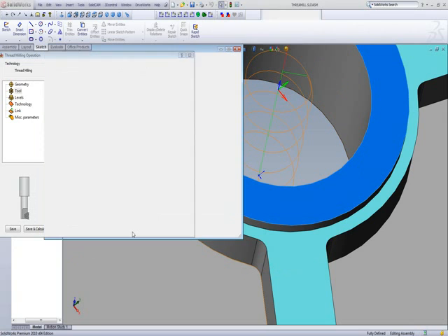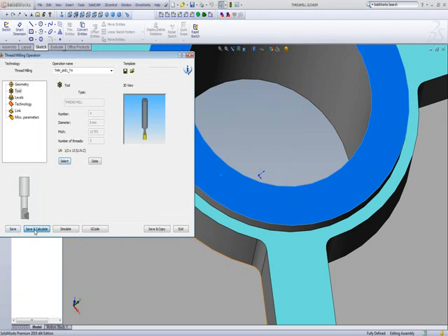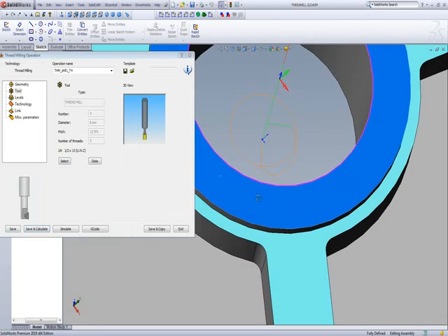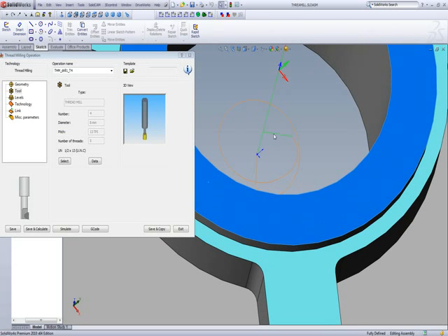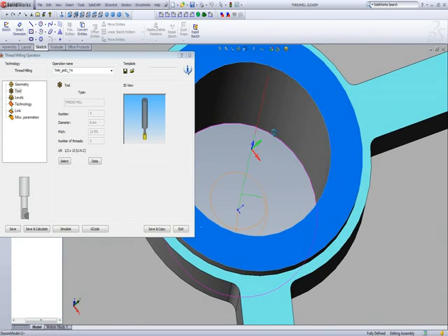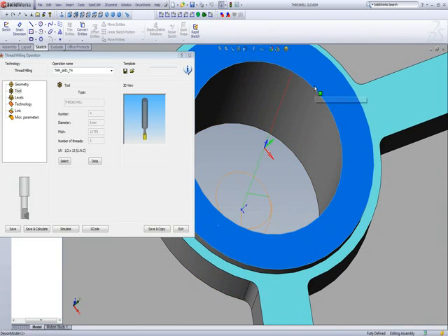Let's take a look at what happens now at the toolpath itself. You'll see that the toolpath now spirals in once and only once. This is because the amount of teeth can now cover the entire wall of the hole itself, so we only have to go around one time to do all the threads on the part itself.